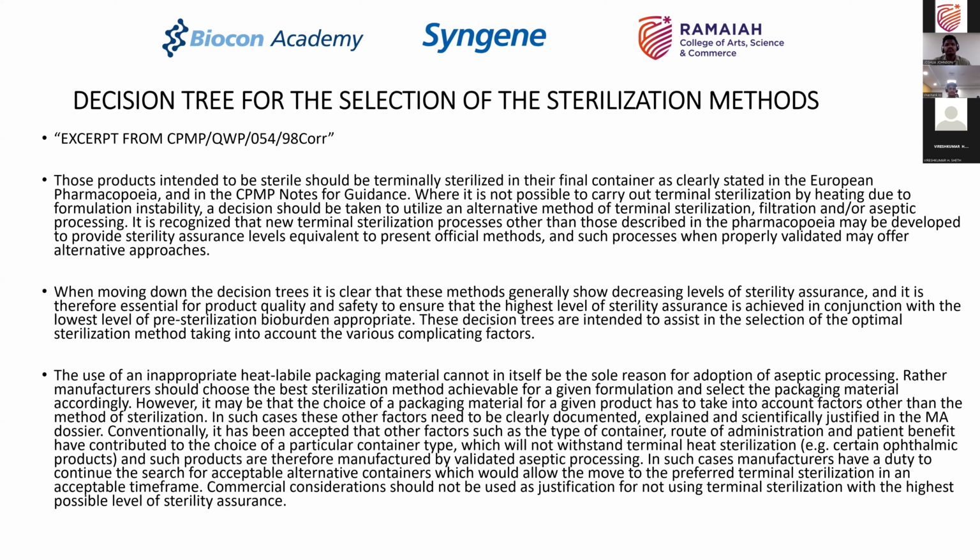Okay, so now, what does the guideline say? It says that even if you were forced to choose the aseptic process because of the container you choose, like in case of ophthalmic processes, it is the duty of the manufacturer to keep on searching for material so that you can move to terminal sterilization.